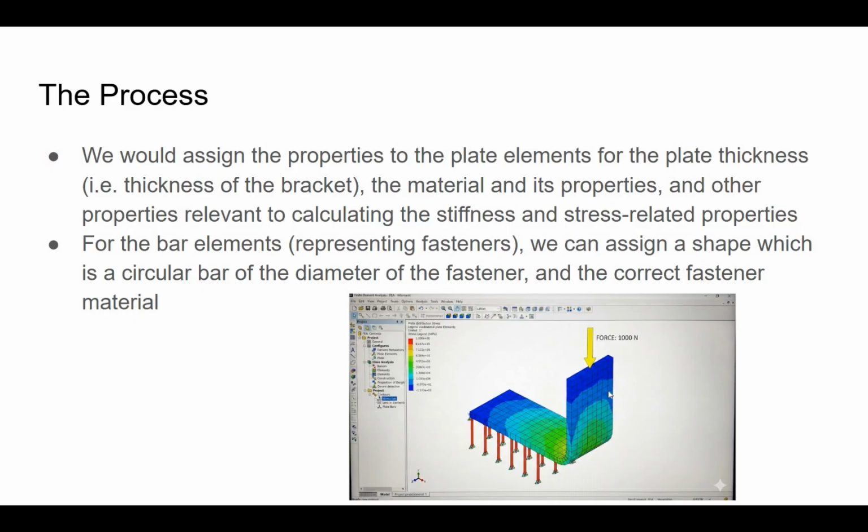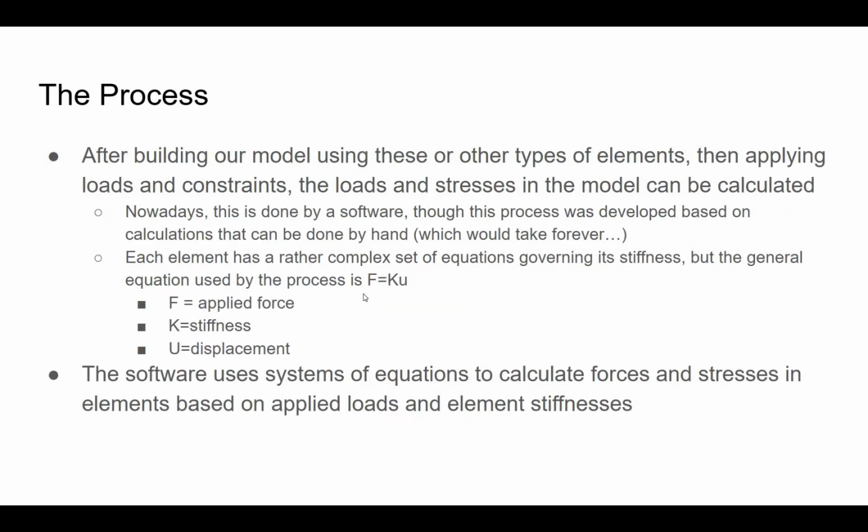And like I mentioned, for plate elements, it's plate stress or planar stress as well. And then for bar elements, it's going to use more of the axial loading to calculate axial stress, shear loading to calculate shear, as well as bending depending on the length of the element and such.